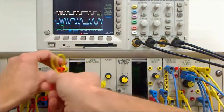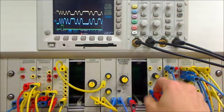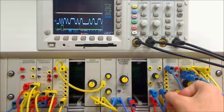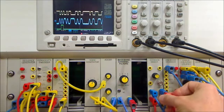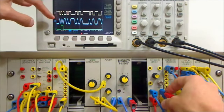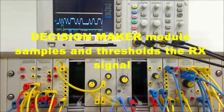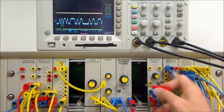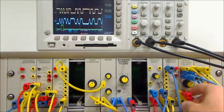Okay, we have our noise, then the noisy signal goes into the decision maker, and we set up the decision point as we discussed in the other video, which I refer you to. It's from the manual D2, experiment 1. Coming out of the decision maker is the signal after it's been sampled and cleaned up. That signal is then passed through a line code decoder module and comes out as a TTL signal.